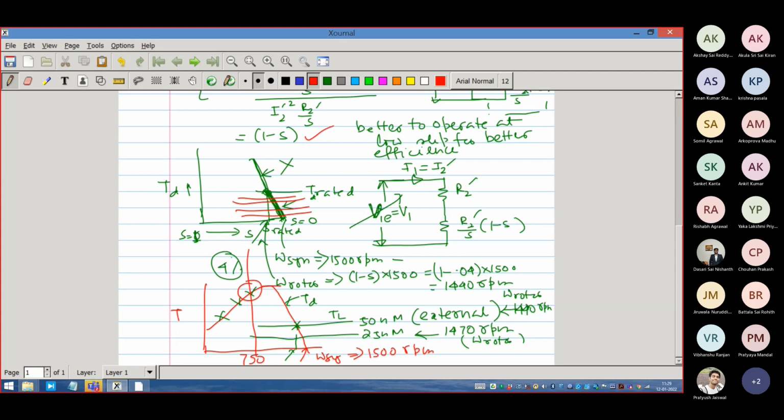Maximum torque, don't misunderstand the maximum torque. This is the physical maximum torque that it can produce. But the rated torque implies the torque at which it would like to operate, beyond which it is not thermally viable. Beyond which it is not possible to operate in the steady state. Momentarily, it may go to that torque. Momentarily the machine will undergo some extra thermal loss, but it will recover, provided you have quickly come back to the zone where there is less amount of loss in the machine and the efficiency is better, right? So let me take another page.